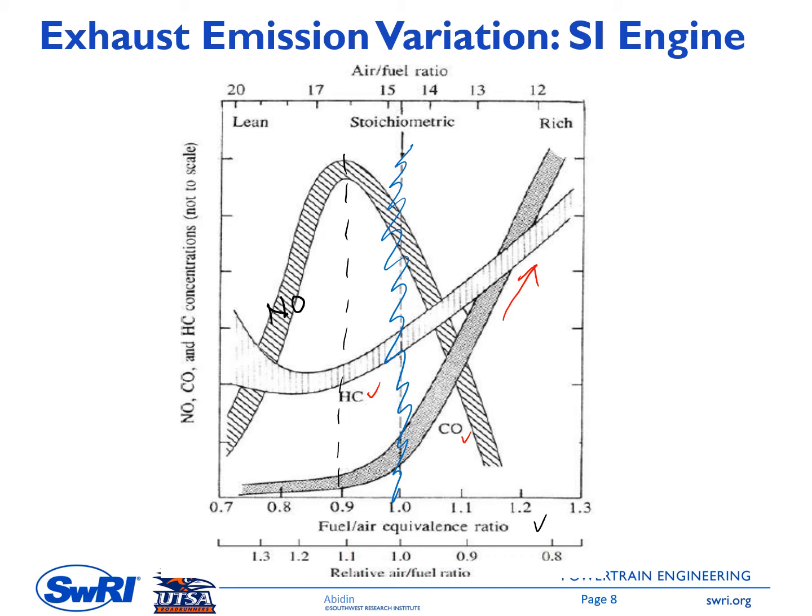So having more air, which means having a leaner mixture, will increase the NO emission. However, as we have a leaner mixture combustion, the combustion temperature decreases. So this is the point where the NO is maximum. It is at phi around 0.9.